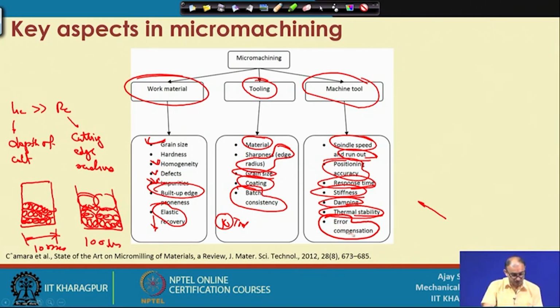If you can calculate the error compensation, then when you target a particular location where your tool is located, what happens is that once the temperature is different at different parts, the machine's temperature sensor will calculate those temperature differences, and these differences will be transferred into the motion controller, and the motion controller will again target this particular part to the actual location. So, at that time, the error compensation is related to temperature compensation.